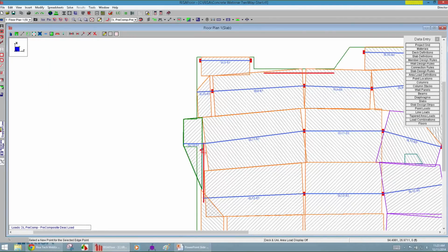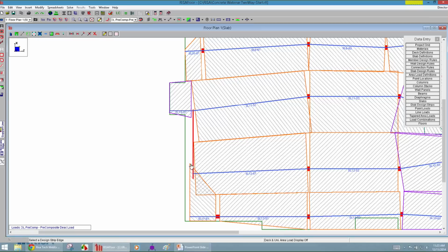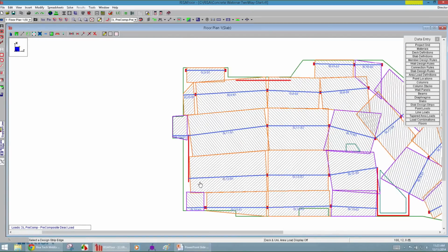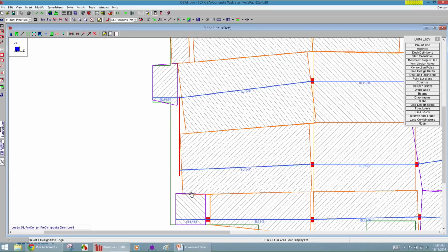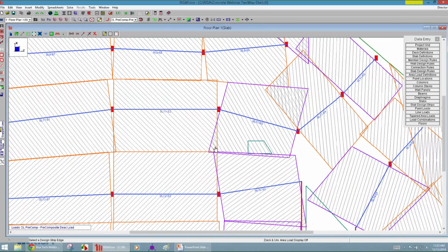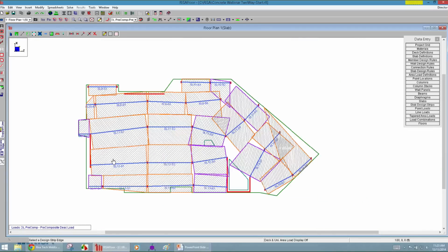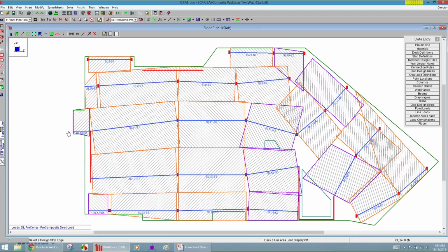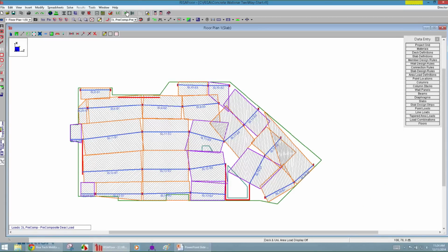So if some of these are kind of big and they overlap a little bit, that won't really hurt you anyway. Maybe it will double dip on top of that, which means that you'll get reinforcement in overlapping. Not a big problem. Some of these you'll notice happen anyway. You get little gaps here and then you overlap on that side. So by the time all this is said and done, you've worked through it. If you really wanted to, you could straighten that out and just have it extend cantilevered. That would be okay. You can draw cantilevers around. You don't need to connect support line to support points. You could actually cantilever, as you'll see I did on the left side. But it makes a little bit more sense.